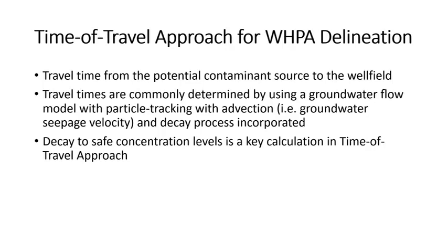Travel times are commonly determined by using a groundwater flow model with particle tracking with advection. By advection, we model the groundwater seepage velocity, and by particle tracking, it means that we incorporate the decay process.